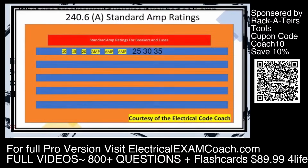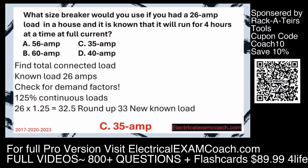Then we head to table 240.6(A), and we choose the next size up. And in this case, it's going to be a 35 amp breaker. Great job.